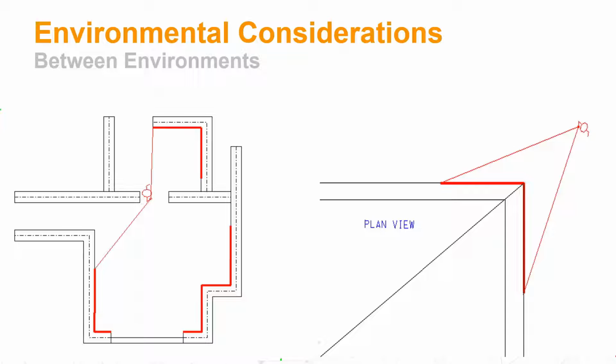If possible, open the door before you do the scan. This way you can transition smoothly, and you will also avoid those opening and closing door ghost points in your point cloud.